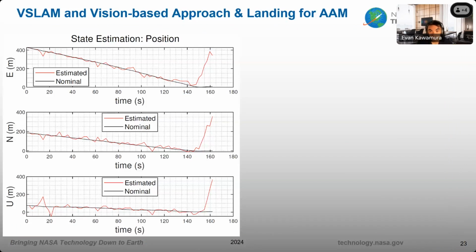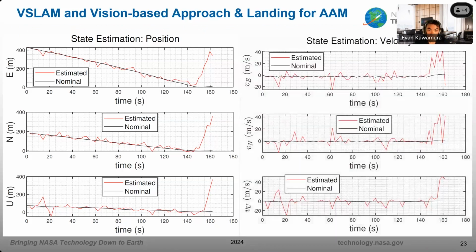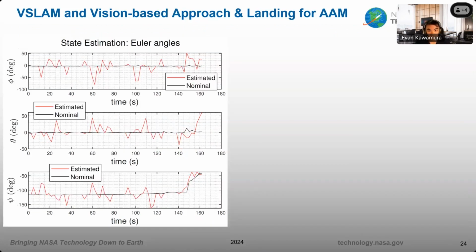So we have fairly accurate position estimation until we land because all the cones and helipad markings are behind us. So that's why we see drift and divergence at the end. As we get composite measurements, they kind of come in and out, the drift kind of goes up or down, and that leads to fluctuations. And we see a similar story for velocity. Overall, our orientation estimation is pretty good. There are some fluctuations because we don't get consistent composite measurements.